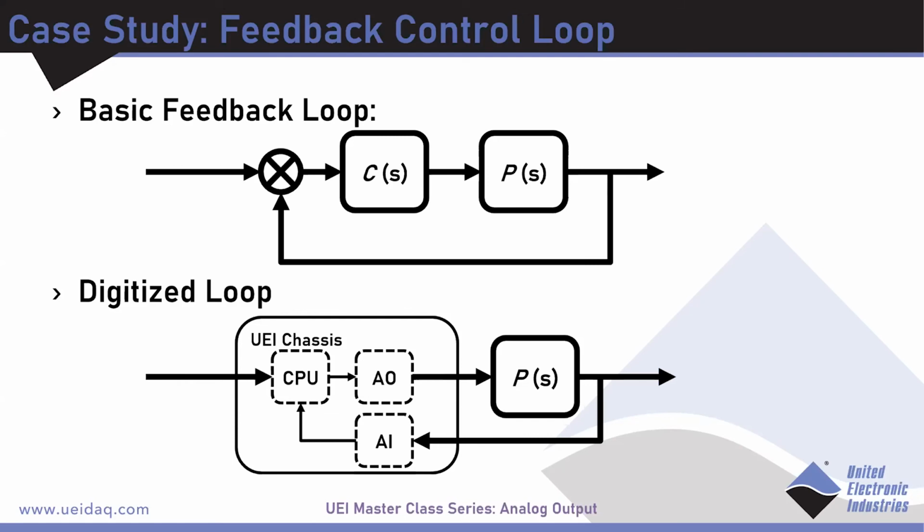Okay, next question. Can I drive a speaker with an AO board? All right, that would be another it depends kind of question. It's definitely possible. I think the main concern there is that because inductors have such a high inrush current, the main concern is ensuring that the board you selected can supply that current.